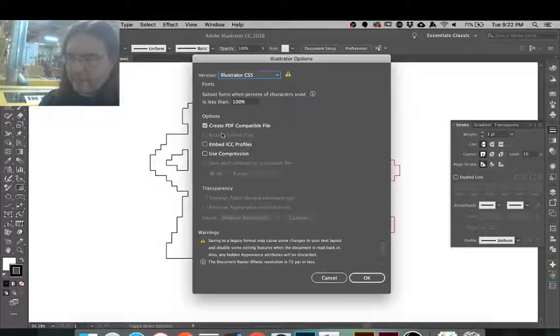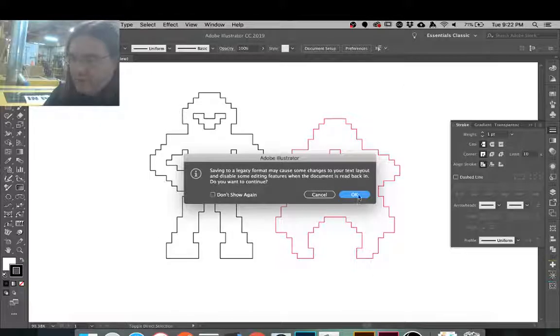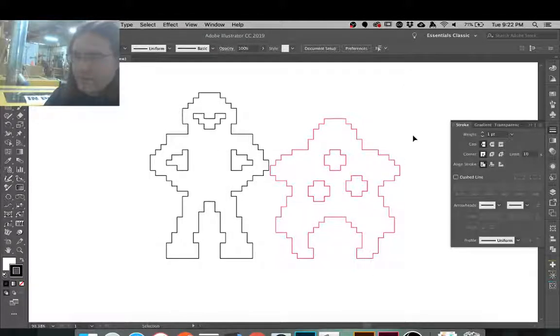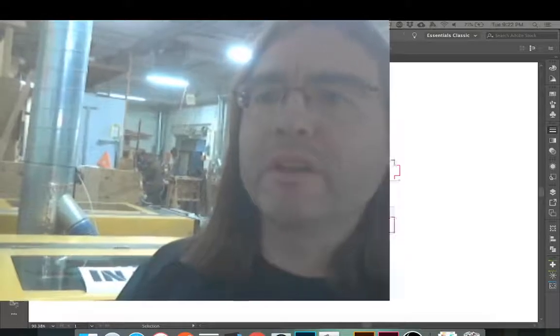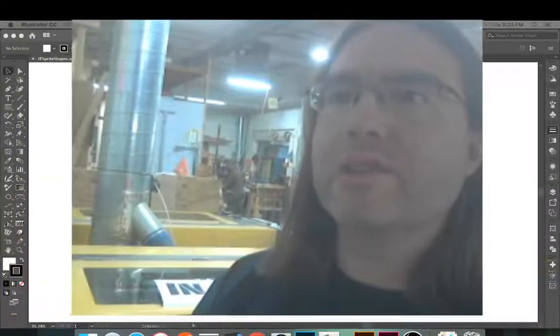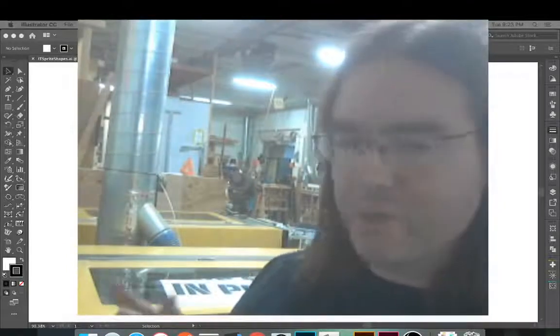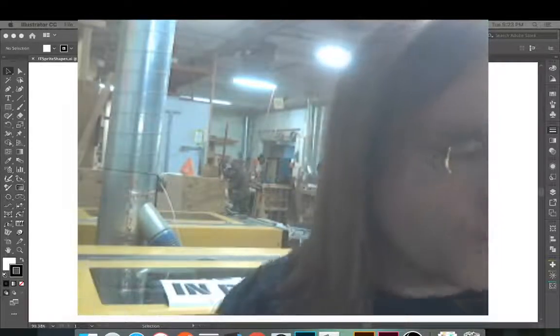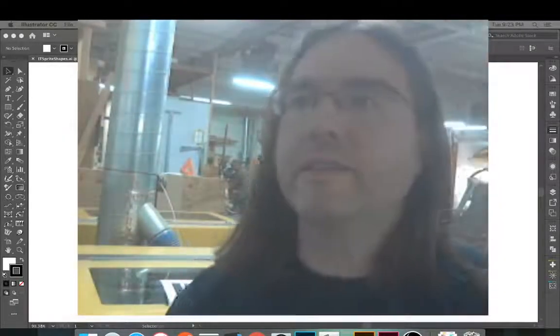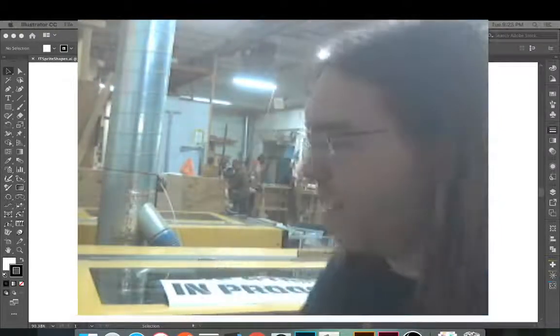LaserCut 5.3 is this piece of software from China where this laser cutter was made. And it has these hilarious error messages that are really not helpful unless you've had years of experience where people finally figured out what it meant. Like, soft dog, no same. Soft dog, no same would be if I tried to load the laser cutter software, but I didn't turn on the laser cutter, because it has a USB key dongle. It's actually a copy protection. By soft dog, they mean the software dongle they need for copy protection is wrong. So they would say soft dog, no same.